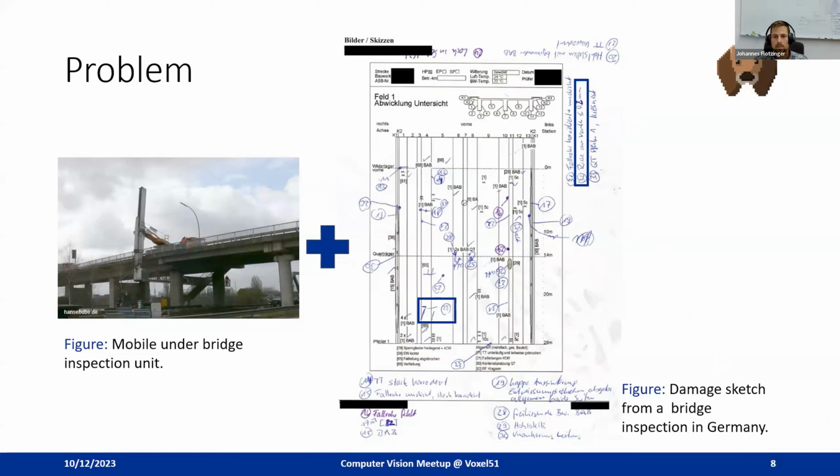After the inspection was completed, some inspectors additionally transferred the handwritten sketch to a CAD sketch. Finally, the assessment of the building is determined by calculating the condition grade, which is similar to grades in school. And the inspector prepares the inspection report. In the inspection report, all defects are listed, including their grades and recommendations regarding restoration, traffic load limitations, or building a new construction, which can also be one case.